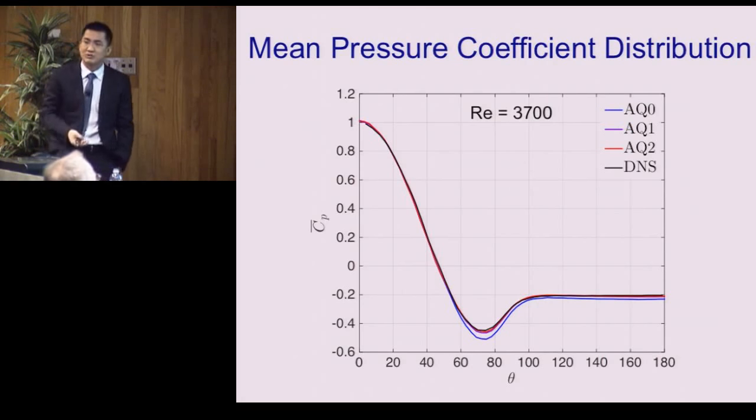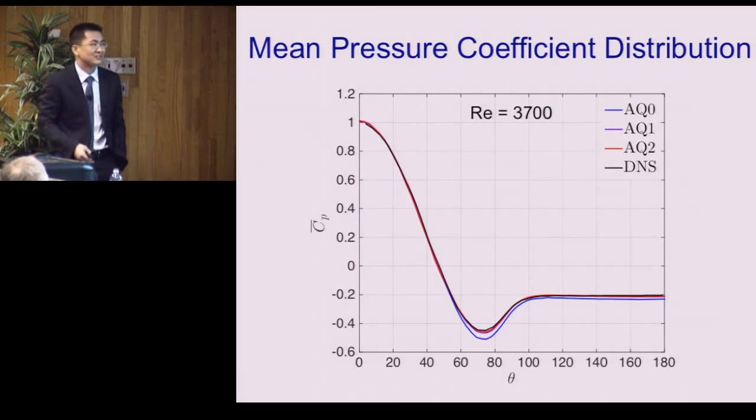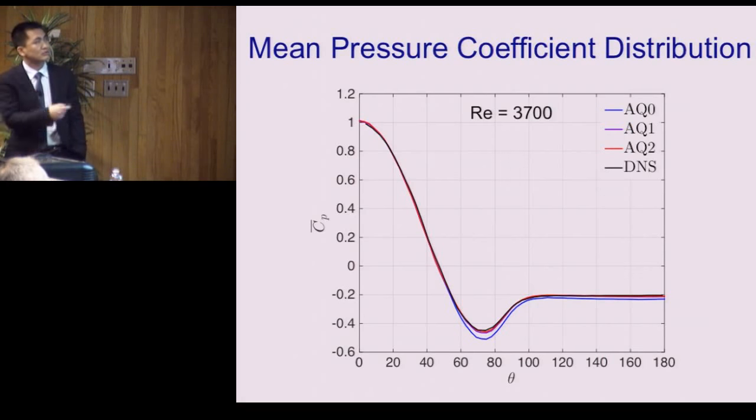So it must be the viscous force, which is usually notorious for a non-boundary fitted type approach. Okay, so that is the direction we are going to look at to improve this non-boundary fitted approach for high Reynolds number flow.